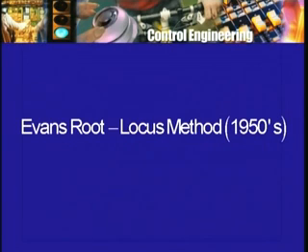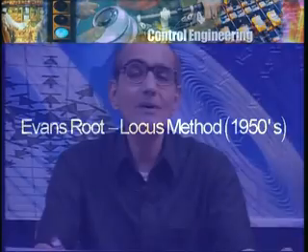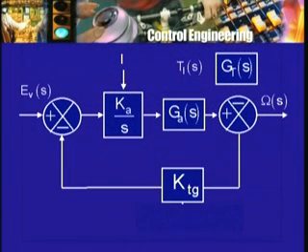So what we are going to discuss applies to a more general class of systems, however, which look like the system that we are looking at, namely there is an output, there is an input, and there may be two inputs. One is the reference input or the true input, the other is the disturbance. Then you have transfer functions from them, but in between you have inserted a negative feedback which is proportional, and another feedback term applied to that feedback signal is this integrator action. So what we have is called a proportional plus integral control system, or a PI control system.